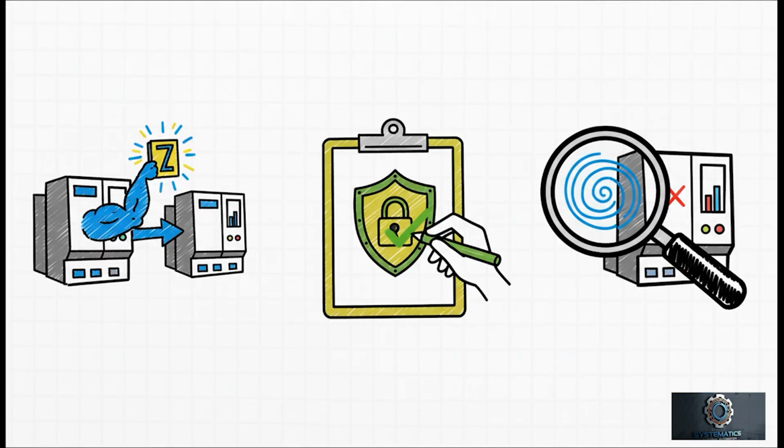So, let's wrap this up with the key takeaways. First, the GET instruction is a seriously powerful and straightforward tool for reading data. Second, setup is everything. If you remember one thing, remember to check that permit put/get access box on the remote PLC. And finally, don't be afraid of errors. Use the error and status outputs. They're not just warnings. They are your roadmap to fixing the problem.